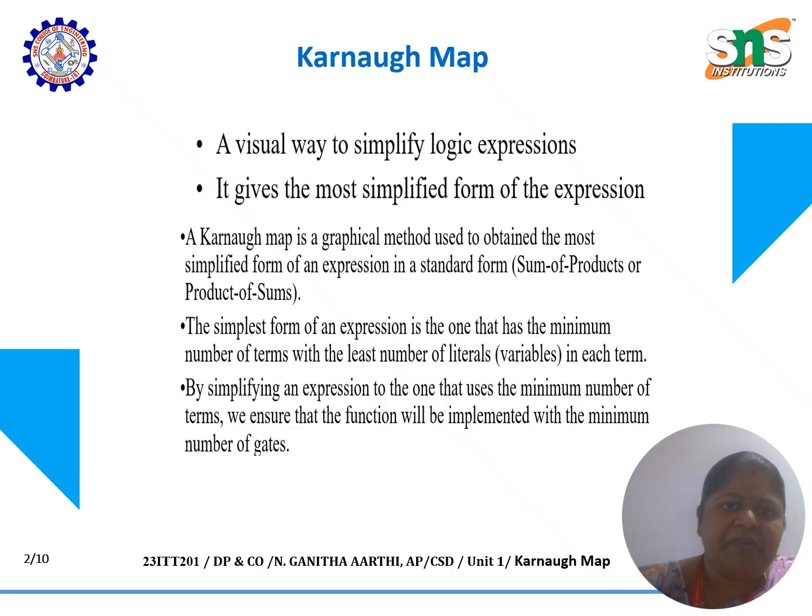So now we'll see the second video on Karnaugh Map, which is K map, a visual way to simplify logical expressions. We use this K map, and it also gives the most simplified form of Boolean expressions. A K map is a graphical method used to obtain the most simplified form of a given Boolean expression. The standard form we use here is sum of products or product of sums.